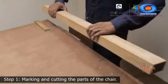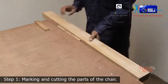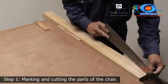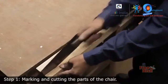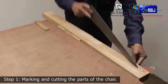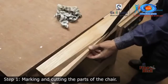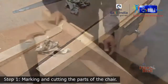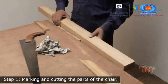Once the layout has been marked, secure the piece to the bench vise and start cutting with a saw. Ensure that you cut along the waste side of the wood, staying within the scored lines. Loosen the vise and swap the side and cut out all the waste wood from the piece as marked in the layout.